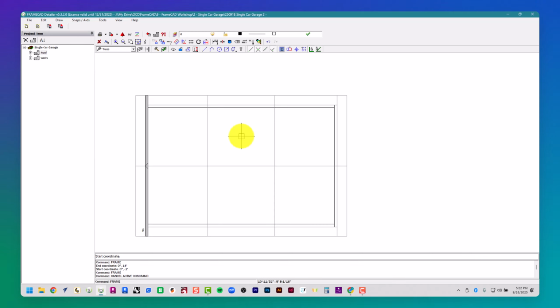While the command is still active, I can continue to create more trusses. I will snap to the end on the far right side, the end at the top side, and then for the side to grip the stick, I will select towards the left and click once. For the 2 in the middle, I will snap to their ends.